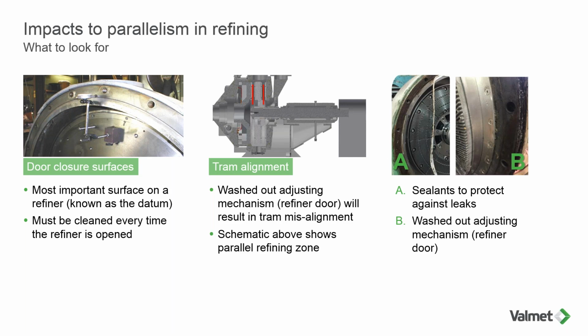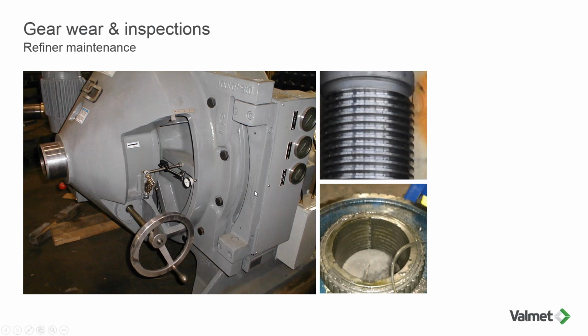And this is when it's time to start thinking, okay, it's time to change out my adjusting mechanism, or it's time to change out my whole refiner, because there is no way for me to understand how good I'm doing other than the fact that my plates started out with 3 months life and now they're down to 10 days. Something that we want to look at once a year as well.